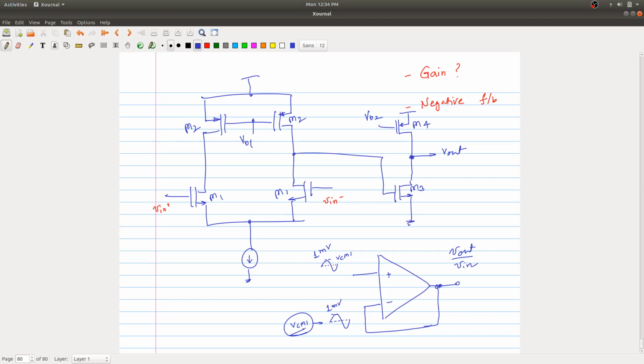And I want to have it VCMI, exactly the same, because you must have studied that if it is an op-amp, whatever you are applying here at the plus terminal, that will go to minus, right? How to make sure that this will happen? It will happen only when whatever the sine wave is here, or DC quantity plus AC quantity, exactly goes there. Let's forget about the AC quantity right now, because AC quantity will be taken care of by this equation when it's in negative feedback.